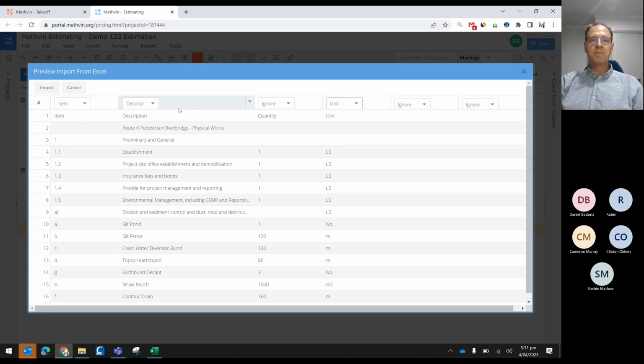So you'll see when we import it, it'll actually give us the total of all these sums, and we call it the hash total, just to check that everything's gone in and we're comfortable that we've imported everything. Because sometimes some of these schedules could be 3,000 or 8,000 line items, and you want to know that every line item's gone in. So if you do a check in Excel, if you highlight that column and do the sum of it, when we finish, it'll tell you exactly. It'll also tell us that there's an error on line 1 because that is text and not a numeric field.